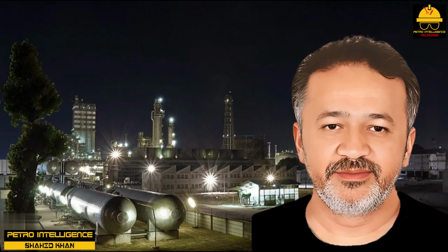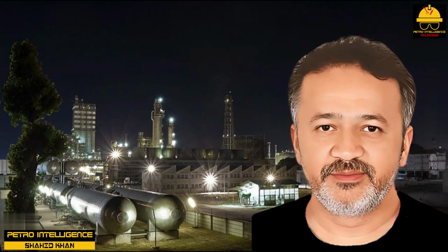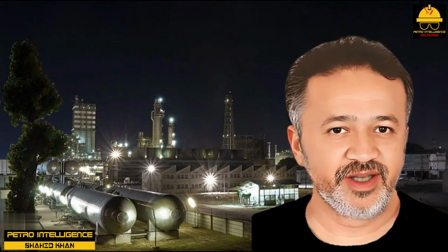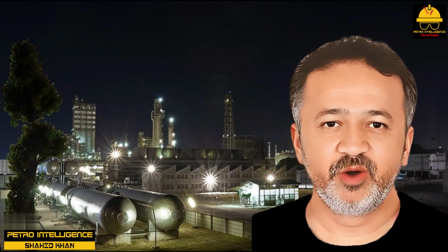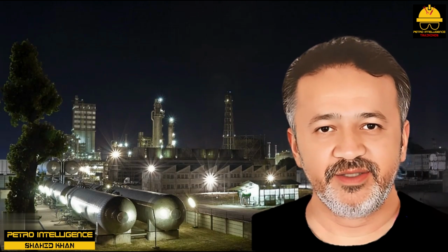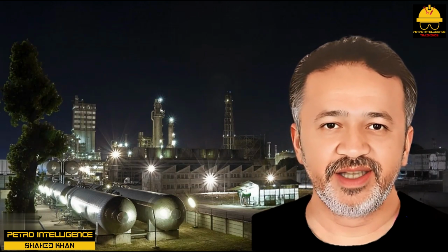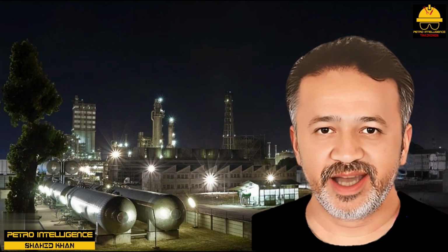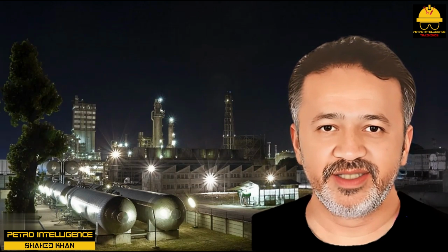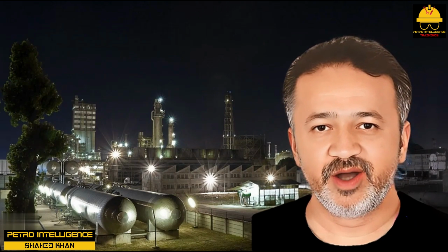Purpose of a catalyst. Increasing temperature to speed up a reaction is often a bad idea. If I have a plant that is desulfurizing diesel oil with hydrogen, so as to convert the sulfur in the diesel to H2S, I can achieve the required percent of sulfur removal in two ways. Mix the hydrogen and diesel together and wait a very long time. Or mix the hydrogen and diesel together at a very high temperature, 850 degrees Fahrenheit. At 850 degrees Fahrenheit, desulfurization will proceed quickly, but the diesel oil will also thermally crack to coke and gas and be useless as a fuel for trucks.